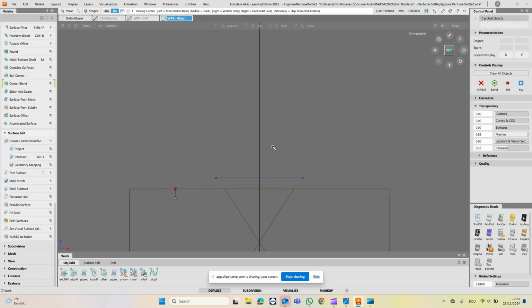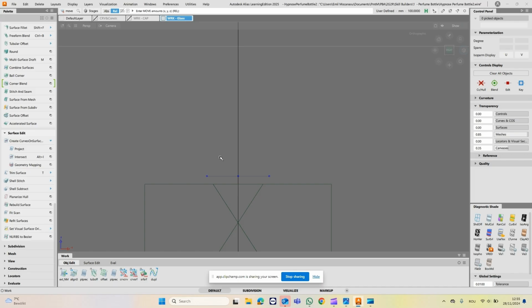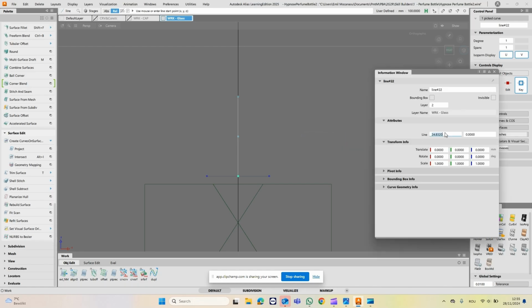What I want to do is, you've seen here we've got these steps, but I want that volume first, so that's what I'm aiming at. And another line, I'll put it dead center now. So holding Control and clicking on that point, going up, and I'll give it the length of 25 mil.